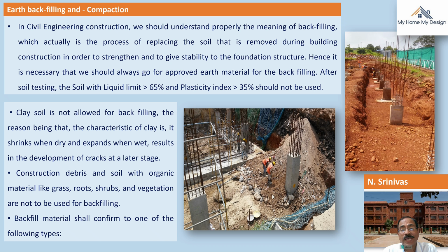So if we use this clay soil as a backfilling material, at a later stage it develops cracks, and as a result the whole soil shrinks, the floorings also go down and cracks develop, and at a later stage it poses a serious problem for the structure also. So that is the reason clay soil should not be used.